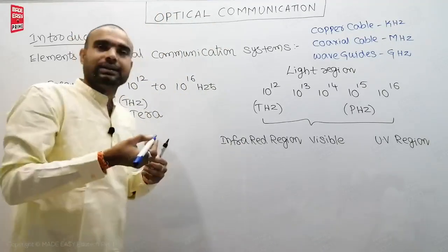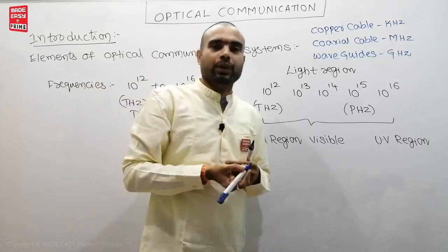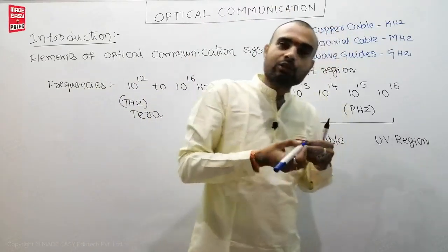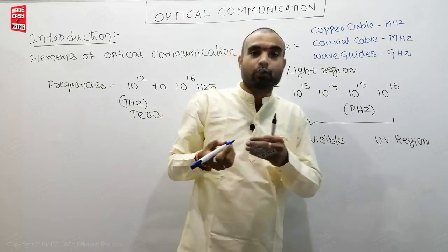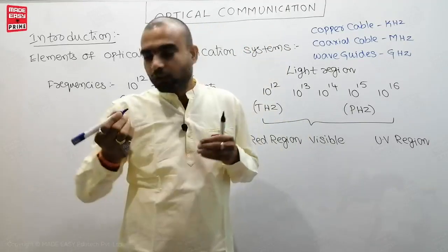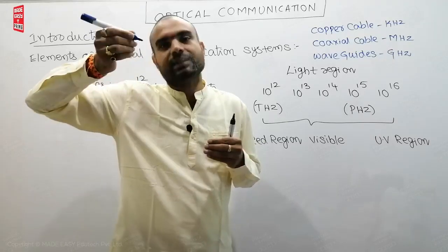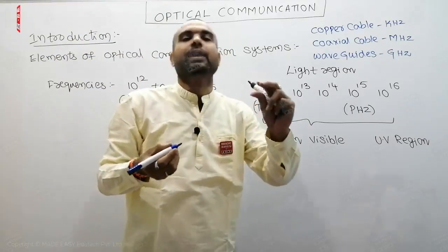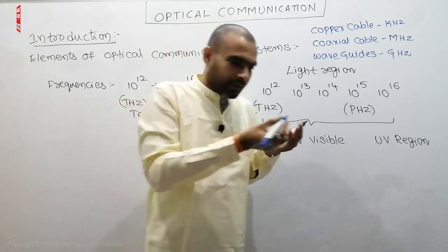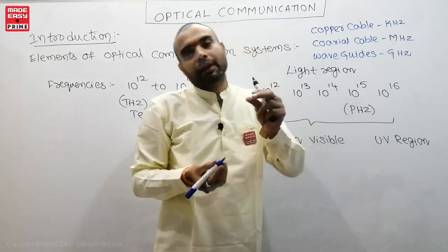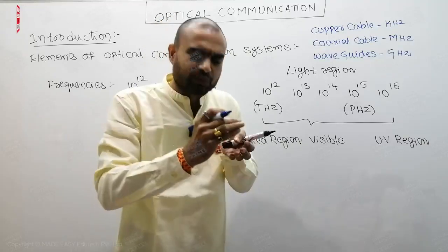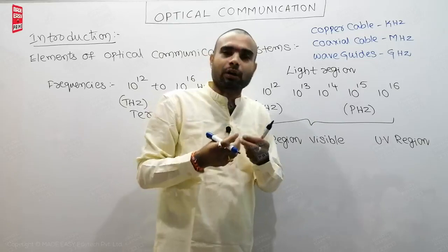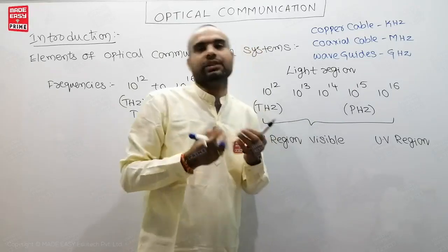After the gigahertz, the waveguides are also not supported, because the dimensions of the waveguide are inversely proportional to the frequency. As the frequency increases, the dimensions become very small. If you consider a rectangular waveguide, the length and breadth A and B will become quite small, and designing becomes a challenging task for an engineer.